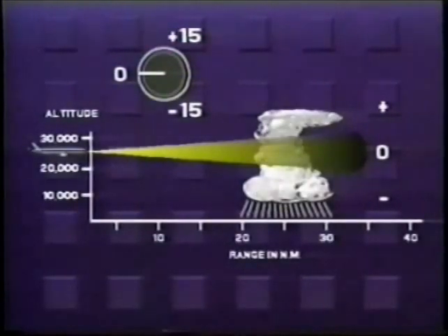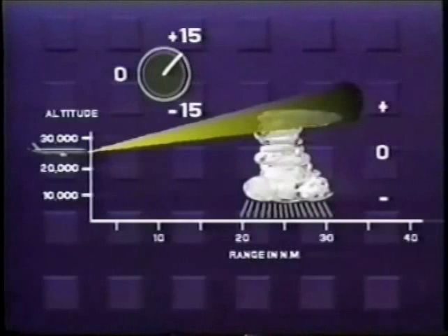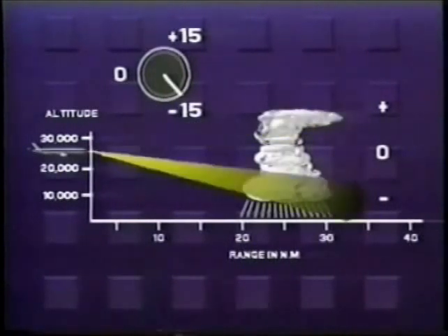The primary purpose of weather radar is to identify and avoid dangerous weather before you are in it. To that end, a radar operator must be able to adjust the elevation beam angle of the radar and know exactly where it is pointing. The antenna elevation pointing angle, commonly referred to as the tilt angle, can be manually adjusted 15 degrees above and below the horizontal plane. This capability allows the radar operator to point the beam of the radar at the thunderstorms